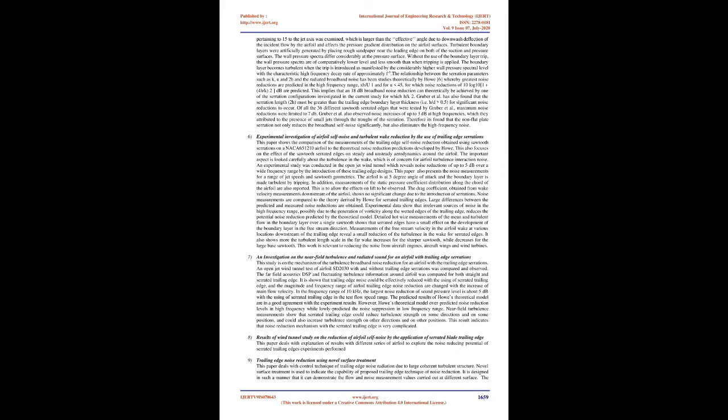4. A trailing edge noise model for serrated edges. This paper is concerned with the development of a theoretical model for the prediction of the sound radiated by serrated trailing edges. The broadband noise, induced by the interaction of boundary layer with the airfoil trailing edge, known as the turbulent boundary layer trailing edge noise, plays a significant role in the overall airframe noise. When a turbulent boundary layer convects past the trailing edge, the unsteady pressure with a wave number in the hydrodynamic range is scattered into sound with wave numbers in the acoustic range, leading to noise radiated from the trailing edge.